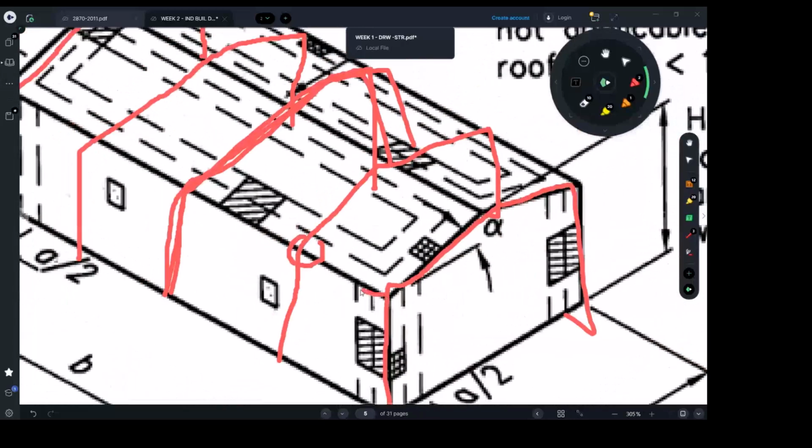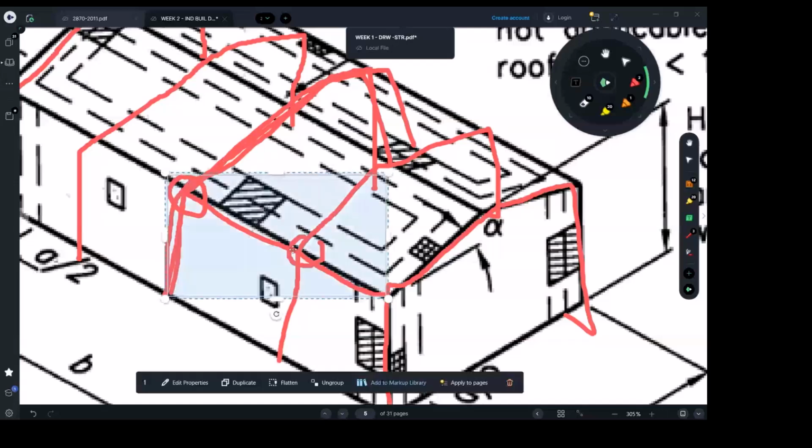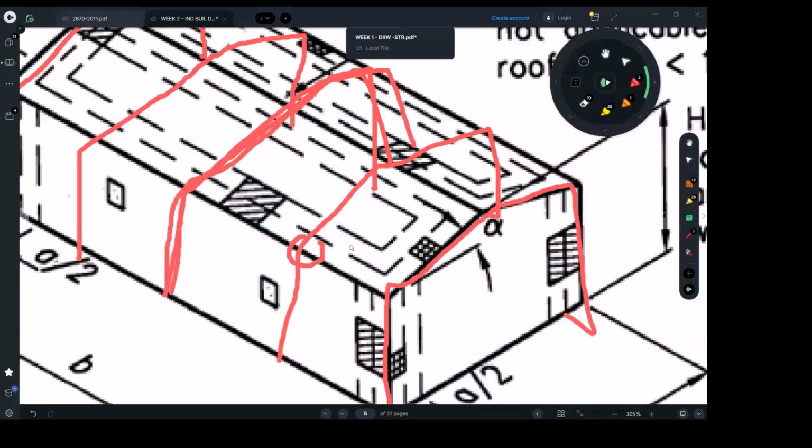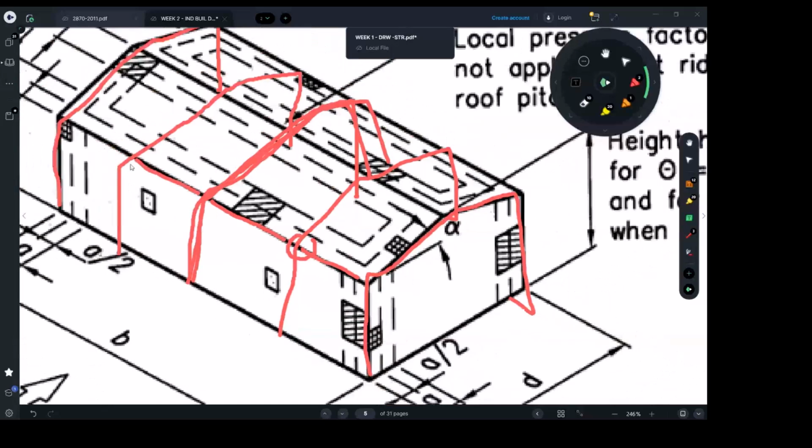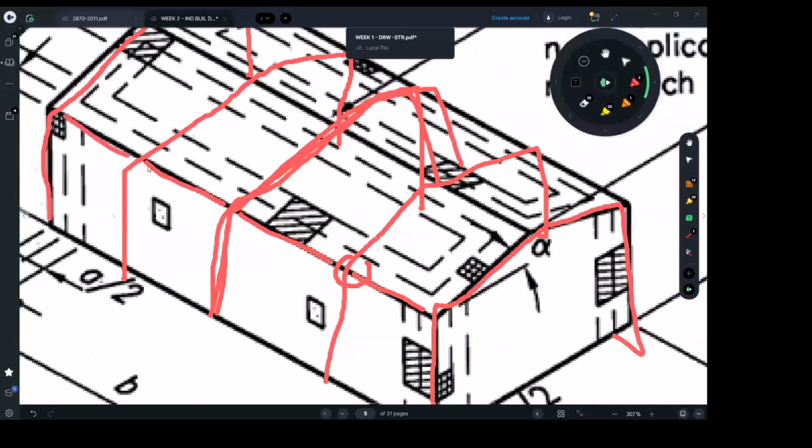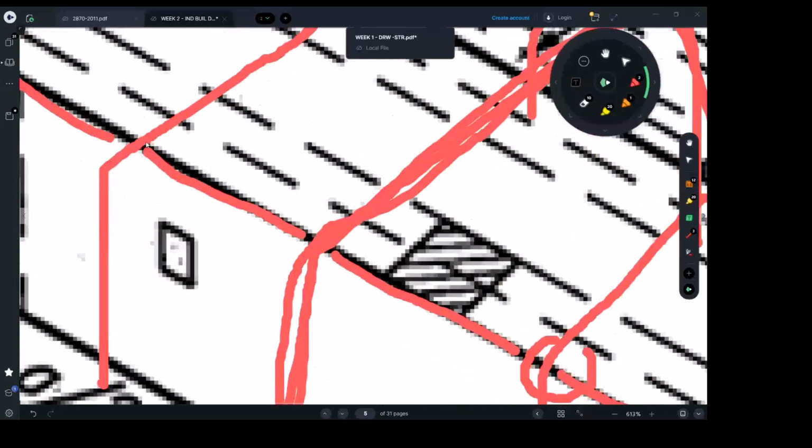Someone will say, can we actually come here and put members and do a lot of welding and all of that? It's going to be too expensive. Nobody does this. So it's not a typical exercise. Yes, it's possible, but usually we're going to have some eave beams. We call them eave beams. They are cheaply connected with the portal frame, with bolts, cheap, not a lot of welding.